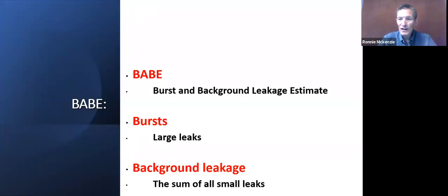Now, we use the BABE methodology quite a lot. You'll have heard of that. The BABE methodology was originally developed by Alan Lambert and some of his colleagues in the UK water industry. It was a relatively simple and pragmatic approach to managing physical leakage in water utilities.